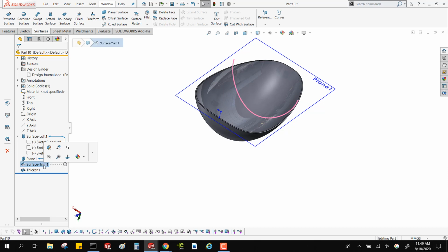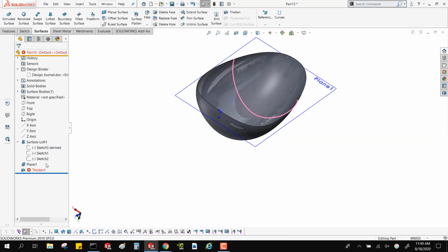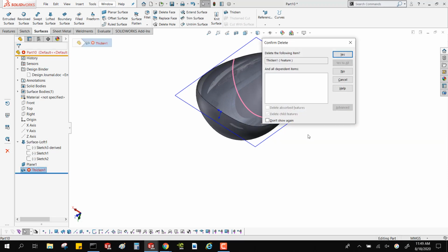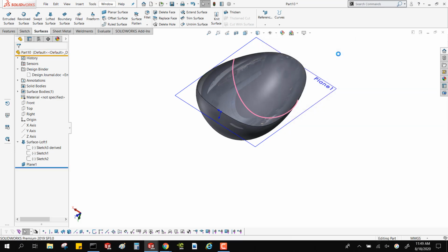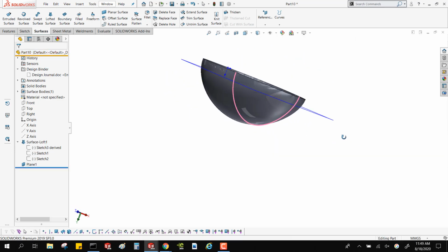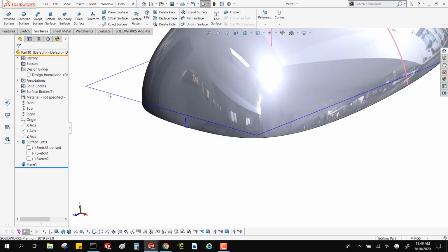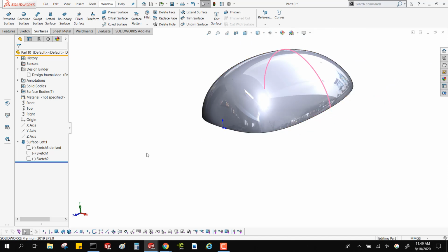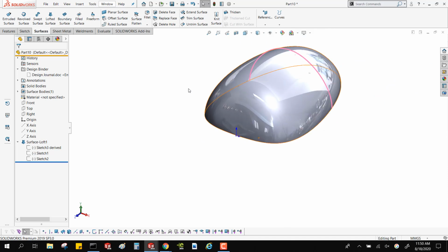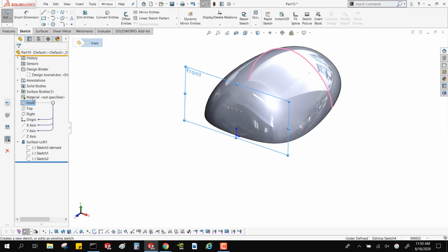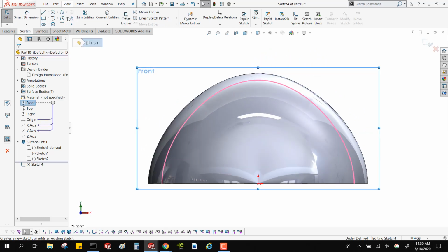The other way. Because I said it's a potential problem, why does SolidWorks even let us get away with it if it's going to be a problem down the line? It's because it's only going to be a problem if that remains. So in the first fix I showed you, I said overbuild the thing and then just slice the convergence point away. The other thing is, what if this was along a pipe or a tube and it's just sort of a bulb that comes out where the convergence point really isn't part of the design anymore once this thing's completely built?